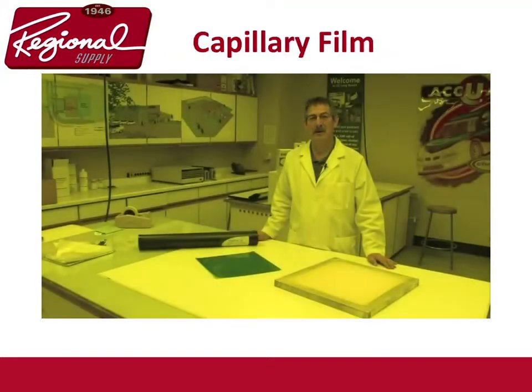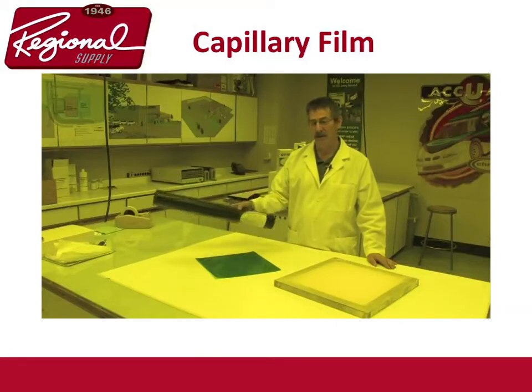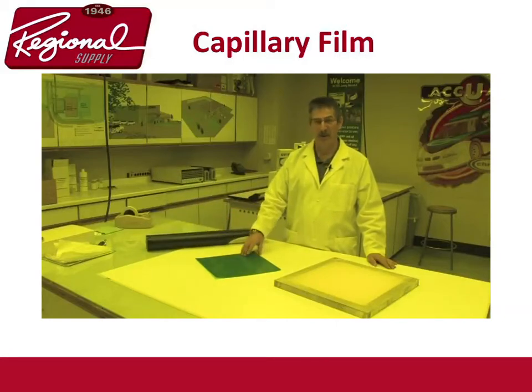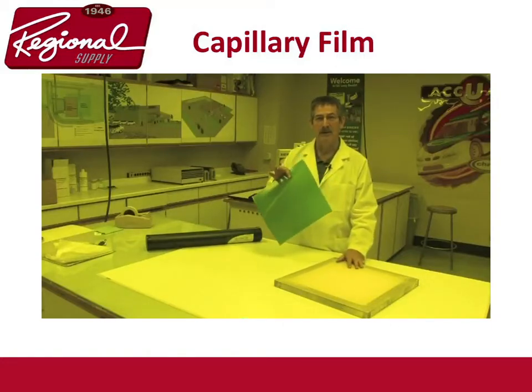Hi, my name is Mick Orr. I'm the Applications Training Specialist here at Chromaline. What I'm going to show you are 2 different ways of applying capillary film. And the capillary film I'll be using today will be our ProCap 50. The first method is known as a roll-down method. I'll be taking this film and applying it to this screen. Let's go into the washout area and apply this film.